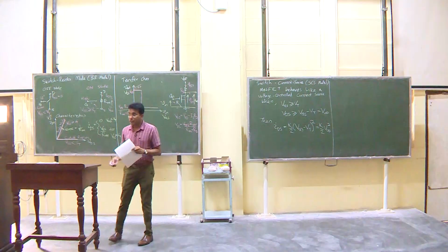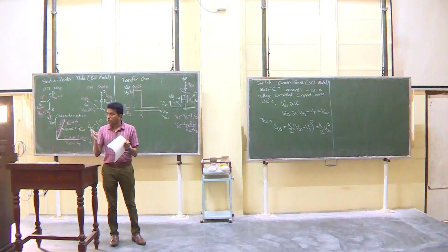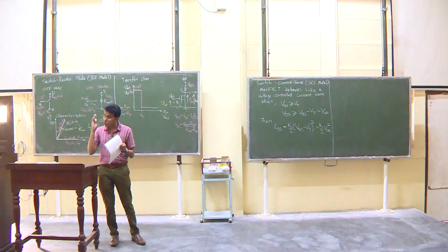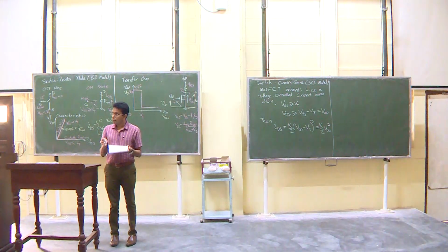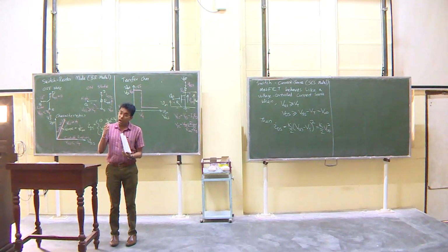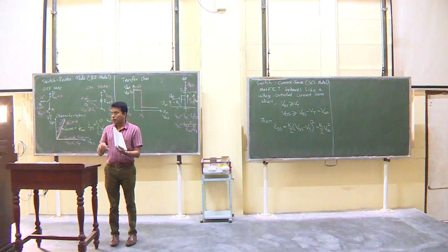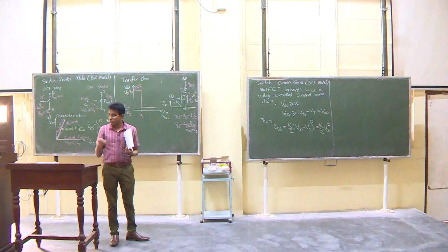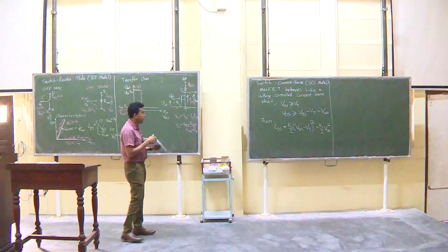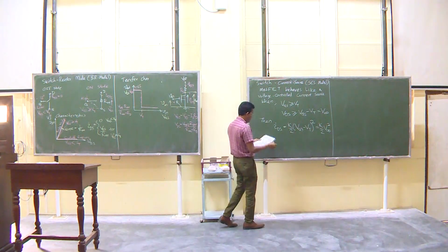Okay, but there is an offset. It's not VGS from 0. VGS starts from Vt. Anything below that, this is off. When VGS is equal to Vt, that is, overdrive voltage is equal to 0, the current is 0. So at that point and below that region the transistor is off. Up to that point it is not behaving like this; it is a switched off switch.